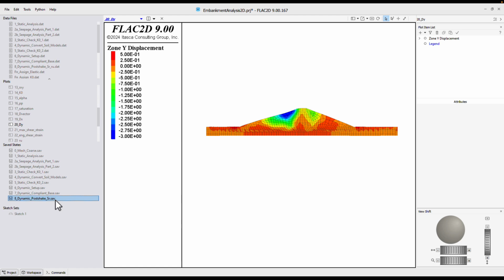I also wonder if we reran the model and instead also in this region that does not have that low strength, possibly if we reduce the strength down here, it could continue to move. But this is the advantage of us having done this more complex dynamic analysis, because based on the state of stress, the expectation is that the material is not liquefying in this particular location because of the lack of stress reversals.